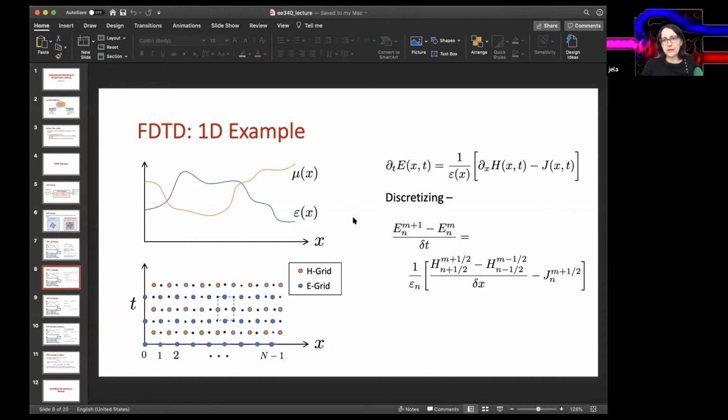If you do a Dirac impulse in time, then that excites all the frequencies, and then you can do filtering. There are filtering methods in FDTD. And since it's a time domain method, you cannot really do frequency filtering, you have to do convolution in time domain. So there are a lot of subtle things that you can do afterwards, but typically what people do is you excite some frequency range where you know your resonance is, and you put these antennas or dipole sources where you know your field would be excited.